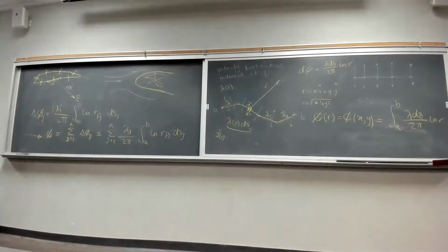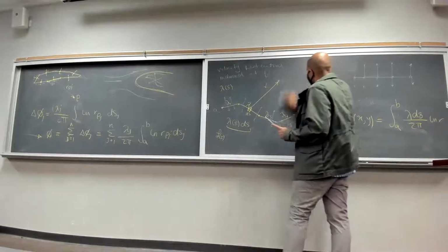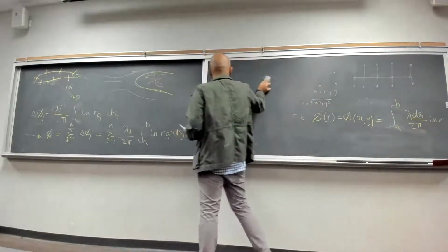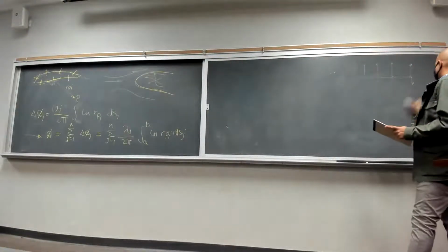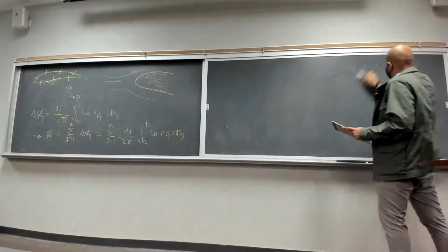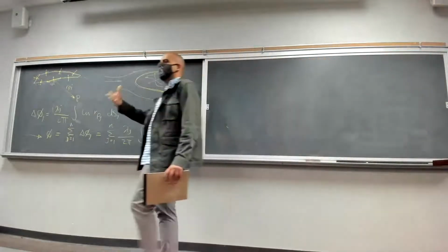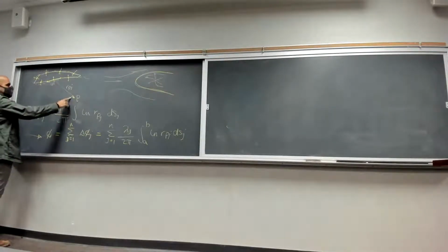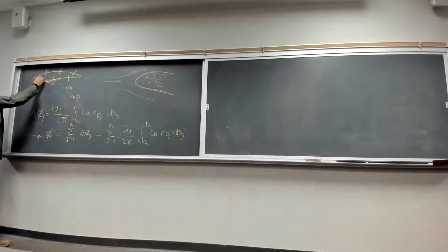So do we have any other questions? Okay. So we have the velocity potential induced by a couple of panels on a point P that is not necessarily on the panels themselves. But the next step, since we only care about what's happening on the surface of the airfoil, because we want to mimic the surface of an airfoil in our flow analysis, is to find the velocity induced by, let's say, this panel on the other panel that is here.